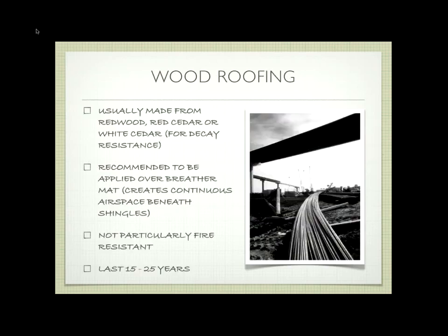The problem with wood roofing is that it is exposed to rot, so you either have to do it out of cedar or you have to do it out of redwood. You're not going to pressure treat shingles. And the other thing is that if you are in a fire danger area, it's really easy to catch a roof on fire, so it's not considered a particularly fire-safe building material. So we're going to tend to use things like asphalt or sheet metal to resist fire.